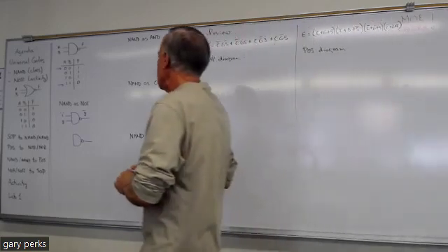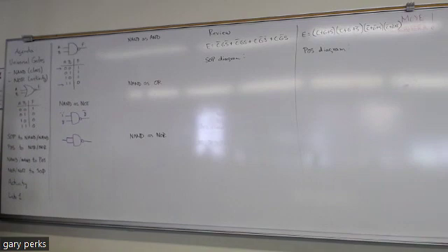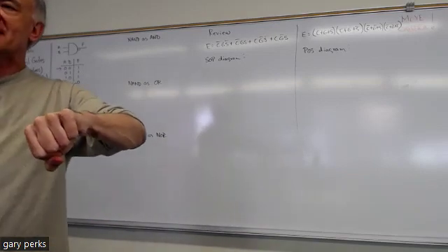So it's the same thing here. I can just do this. Here I've got my 2 inputs. If I short them together, it effectively makes it the same node and they have to have the same voltage. If I connect these two inputs together, they can only be both 0 or both 1. There's no way that one input can be a 1 and one input can be a 0. What happens in a circuit if you connect 5 volts and ground to the same node?